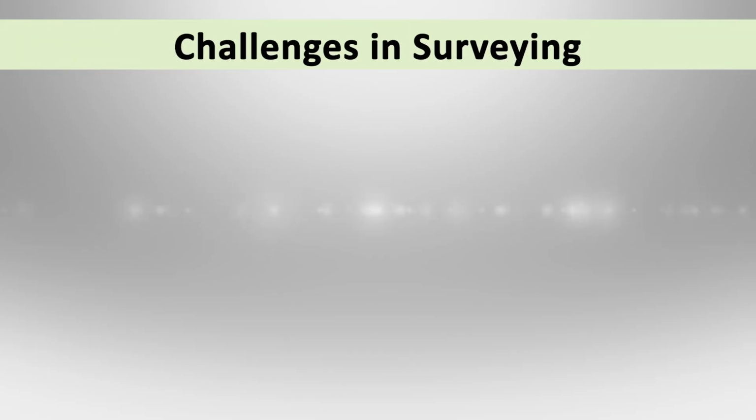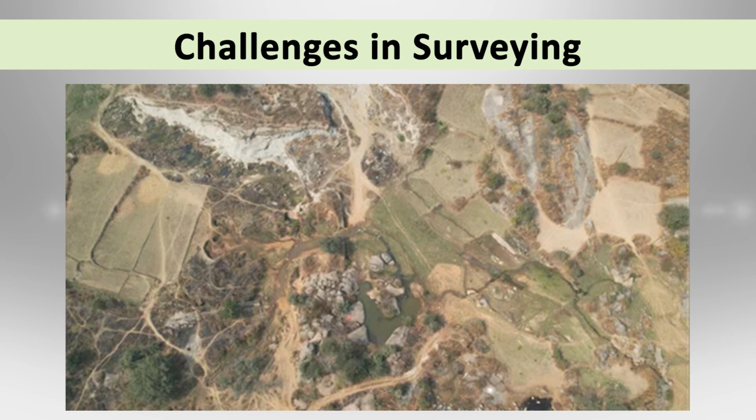During survey work, we encounter various complexities and site situations which are not favorable. Sometimes points are not accessible, sometimes distances are not measurable, ground surfaces may be undulated, or it may be sloping. In such cases, measuring horizontal distance is tedious and sometimes it is impossible. The civil engineers are very smart. They will find ways to solve issues and complete the work by means of direct or indirect measurements. By using the principles of triangles and trigonometry, surveyors can determine the height of locations that are otherwise hard to access.